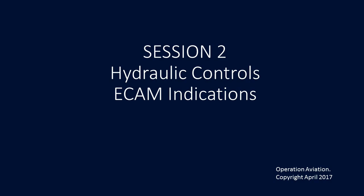The hydraulic indications on the HYD ECAM. Okay, so here we look at PTU status. We're going to obviously have the amber again, meaning that the PTU has been selected off, or the PTU is inhibited, it's not working. An indication with green arrows going right to left means that the PTU is supplying pressure to the green system. An indication with the green arrows going from left to right means that the PTU is supplying pressure to the yellow system.